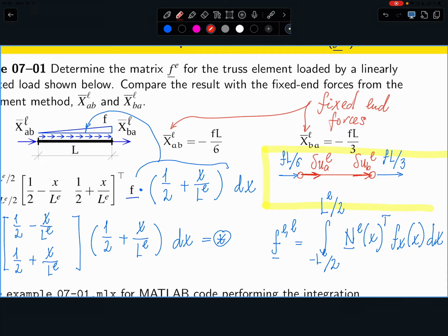So instead of computing this integral, which I have done before, the only thing which you need to do is to prepare this 2-by-1 matrix, pick some particular values of these arbitrary displacements, or take them as parameters, and do multiplication here plus multiplication there.